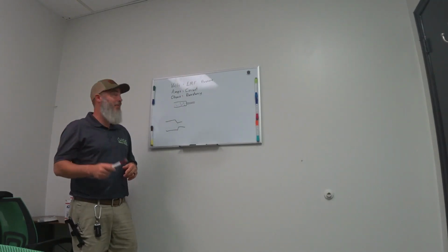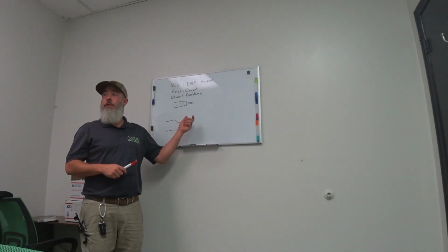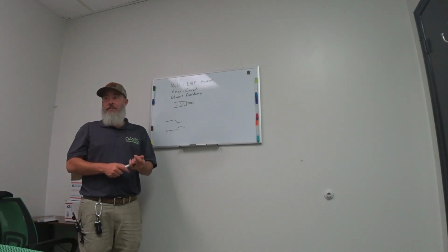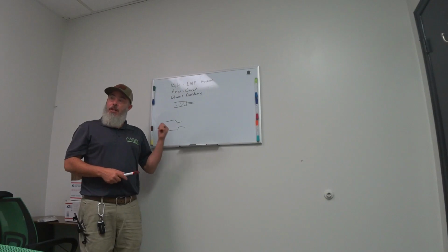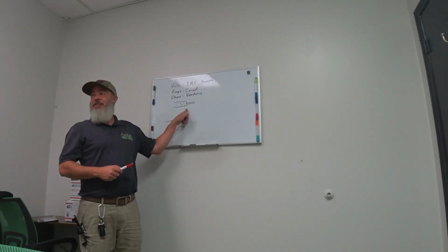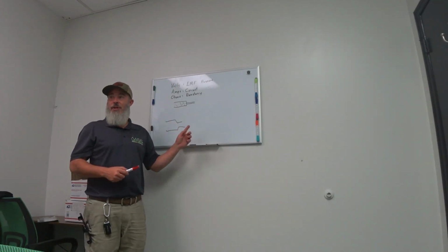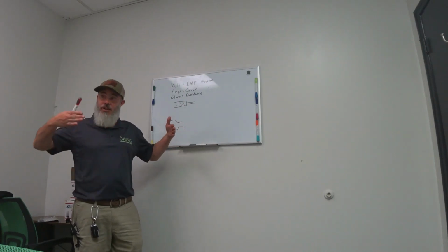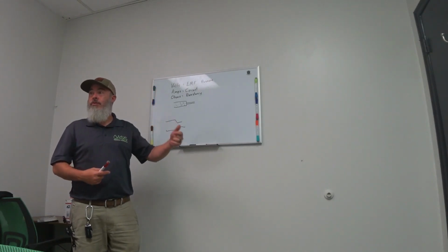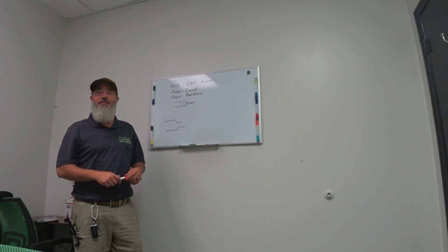Oasis doesn't do that, but you'll see it where some people have done that, and they'll use even a plug that isn't rated. If you have a plug that's rated for 15 amps that you put on there, and this machine's rated for 20 amps, well, now you've got kind of a pinch point. You've created a point of resistance. That's why it's not rated to flow that many electrons. All of a sudden, a lot of electrons are being pushed into a small point. Temperature goes up, burns up the plug, burns out the outlet, and everything like that.